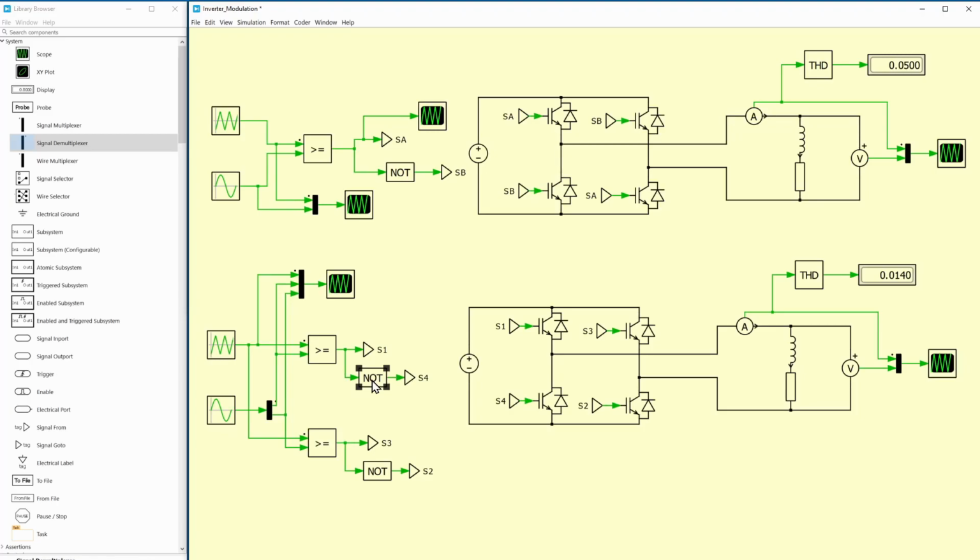Okay, so what we need to do is make a comparison. Now I'll shift the sine wave up by a very small value and compare it to the triangular wave, and this will make sure that we have a wider range of PWM, like the pulse width will be wider at some point, and then we can generate what we call the dead band.